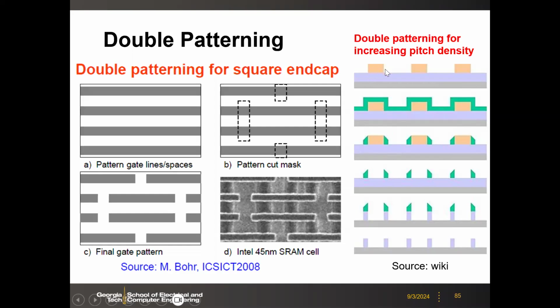You first get some notch pattern using conventional lithography, and then you deposit something, which is like the green layer, covering this step, and then you etch the green stuff, like dielectric, away. But because it etches only the surface, on the side wall of this step, we call it the spacer, you have some leftover of this material.